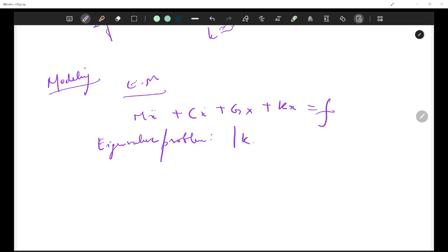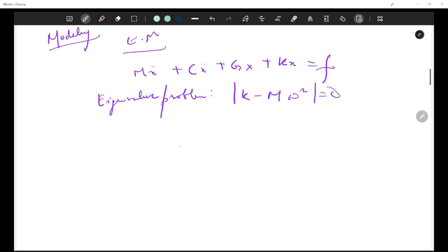We want the determinant of K minus omega square M equal to 0, and the parameters here are RA, RB, alpha, beta and H. I'm not going to detail it. The thing was that we want to minimize K, which is omega max upon omega min. The goal is that all natural frequencies should be equal and the dynamic isotropy index should be around 1.6, 1.7.